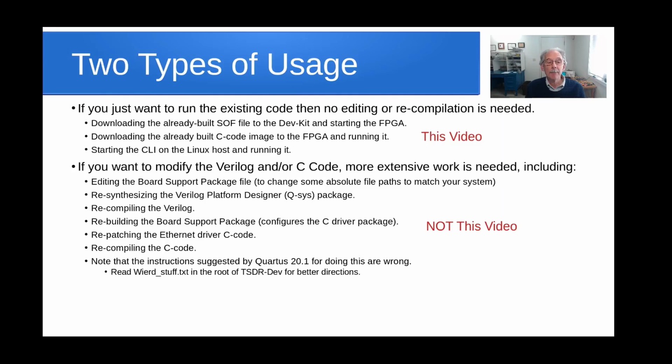You'll need to patch the Ethernet driver code and recompile the C code. That's not the subject of this video. Note that the instructions provided in Quartus 20.1 for doing this are not correct. There's a file called weird_stuff.txt in the root of the TSDR dev directory, which will provide detailed directions for rebuilding the board support package.